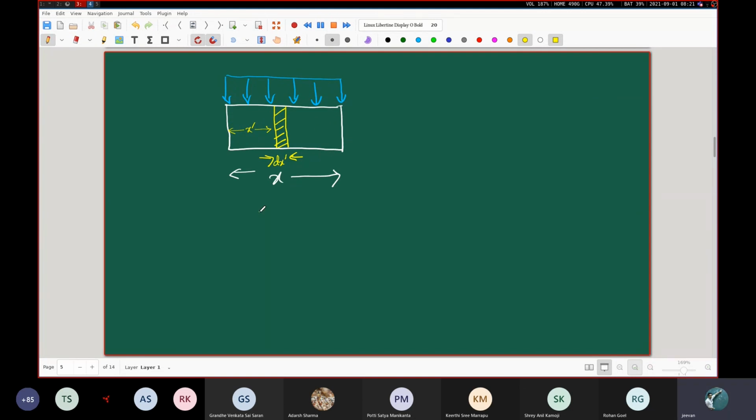As I move this strip from this end to this end, I will be covering this entire distance x. Now you tell me, with respect to this, what will be the contribution to the bending moment as a result of the distribution of forces acting over this small strip dx dash? We are again considering this, right? This is our M, still this is our V. W into dx dash, that is the force which is acting over this infinitesimal strip.